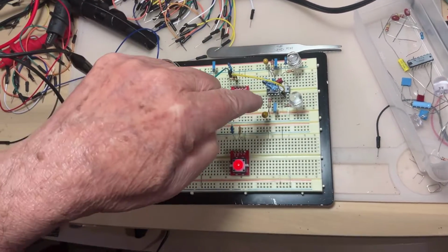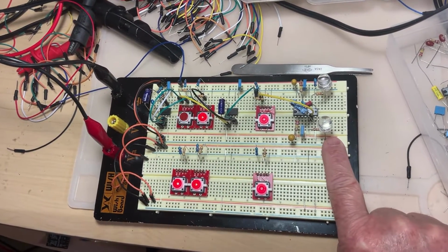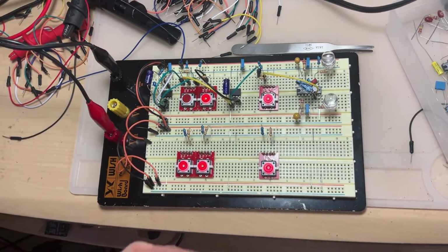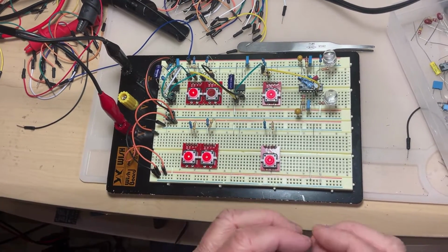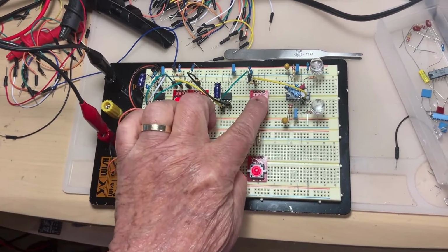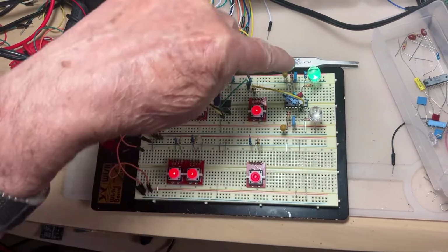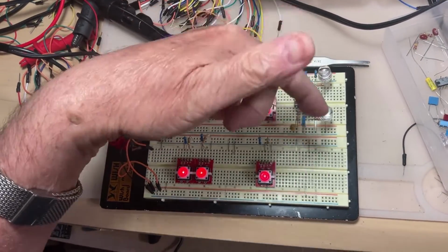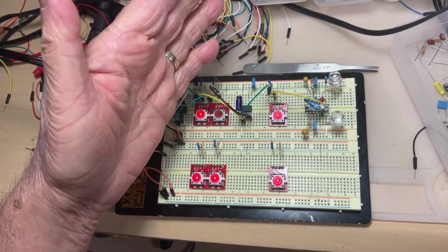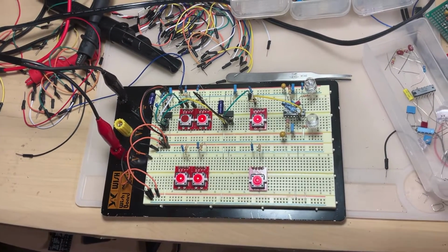However, by connecting 2 of them together, cascading, when this one finishes the operation, it is going to trigger the next one. You can connect or cascade 2 such circuits together, and this is what's going to happen. This one stays on for 2.5 seconds. When this one finishes, the other one goes on for 2.5 seconds, and it goes off. And of course, you can play with the duration of these as you wish. Why? Because we play with the formula. It's a very easy thing to do.